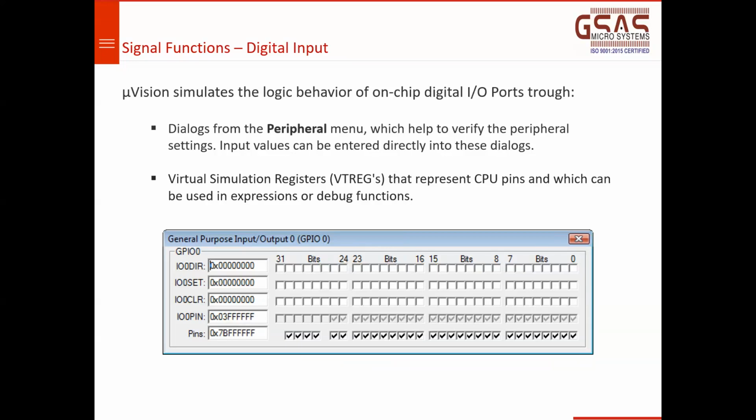Once the pin goes high or low, depending on the processor, let's take low as the example, as that port pin goes low, an interrupt is generated to the processor. That is what we are doing here. You can see it gives you access to the pins. You can directly click on a particular pin where you want to generate an interrupt, and it triggers an interrupt to the processor. Again, here I am simulating the interrupts as well.